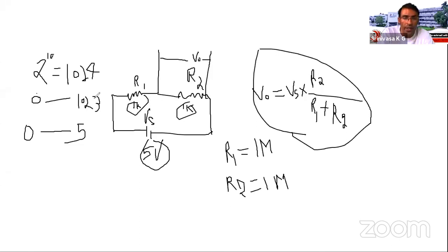If we are reading 1023 from any sensor, that means 5 volt. So we can use it, or we can convert it again into volts if we want to print it in the serial monitor. How can we convert it? If we want to convert this value into a voltage signal, just see, we are getting the 1023 value at 5 volt.